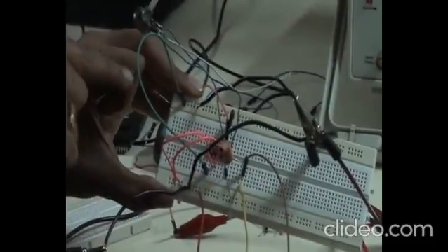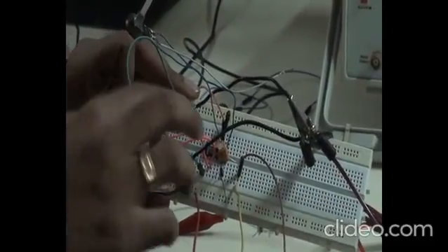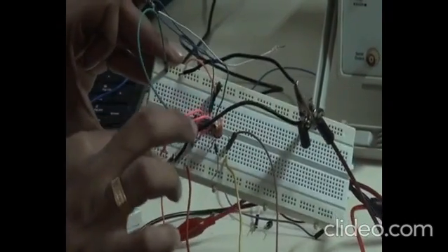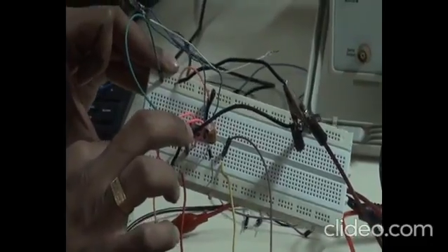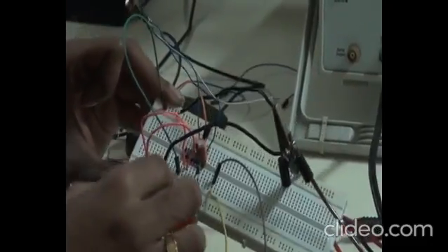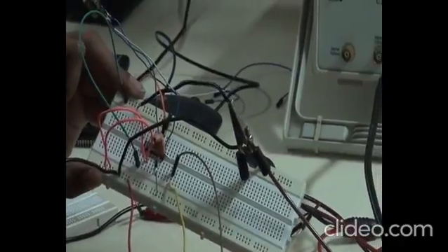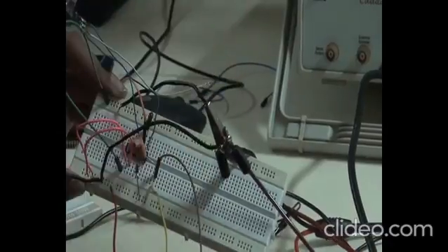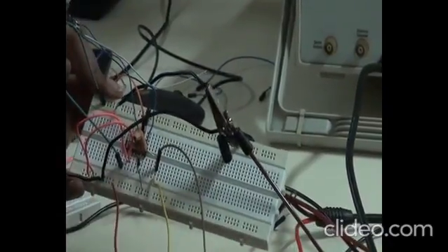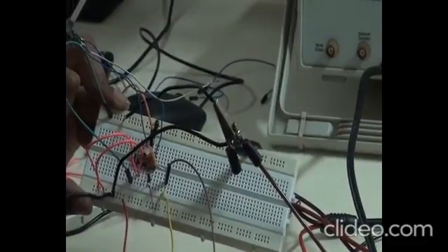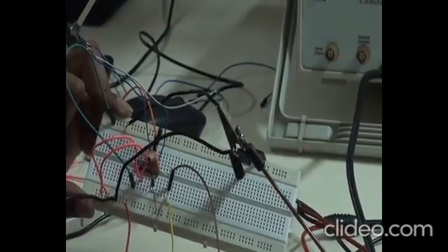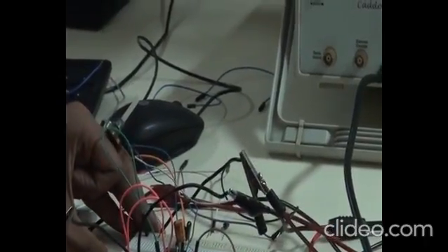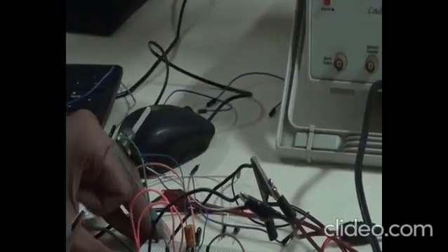Pin number 1 is connected to minus VCC. Pin number 2 and 3 is connected to ground. So these pink colors are actually connected to ground. Okay, and pin number 4 is where you are going to take the output, and that is this particular connection. Okay, and then pin number 5 and 6 you have left outside, and pin number 7 you will be providing the input, and the input is the square wave of 4 volt peak to peak and 1 kilohertz.